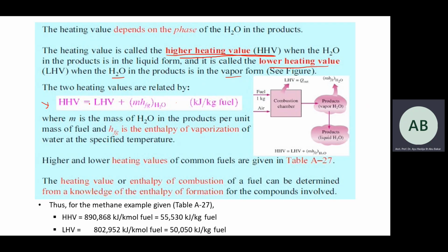So HHV is equivalent to LHV plus m, the mass of the water, in this case we are referring to water, multiplied by the HFG, the difference between enthalpy for liquid minus vapor. HFG is the enthalpy of vaporization.